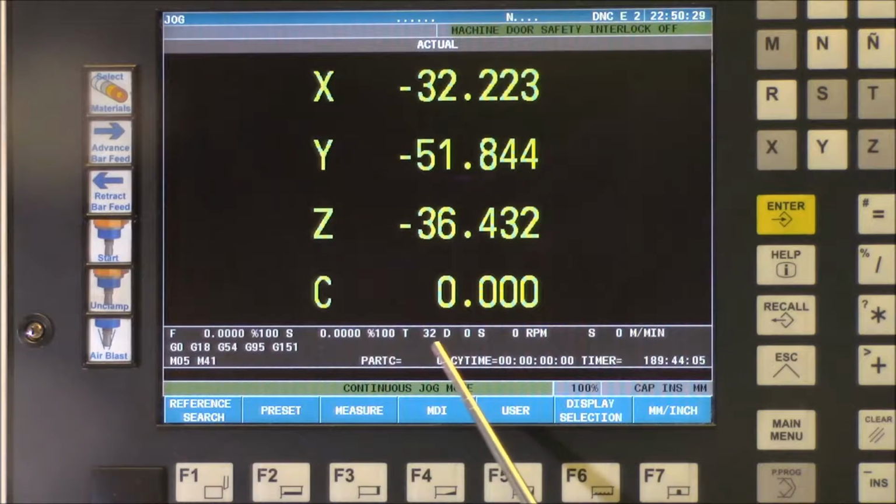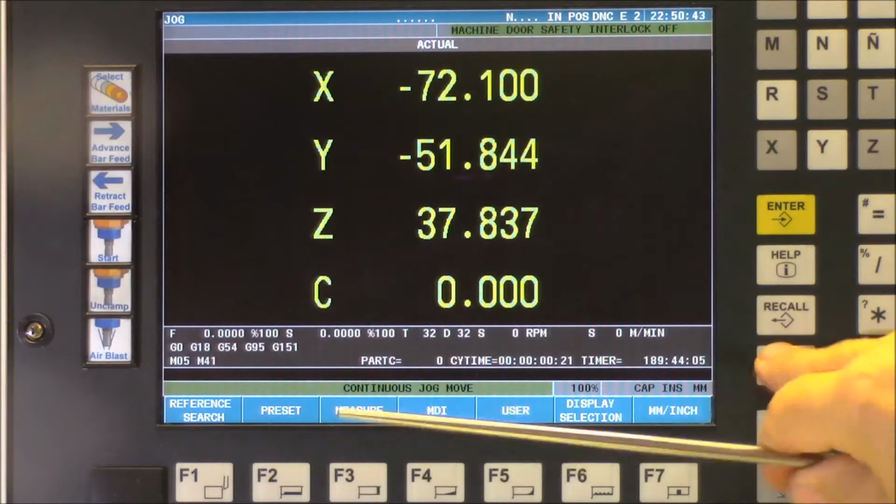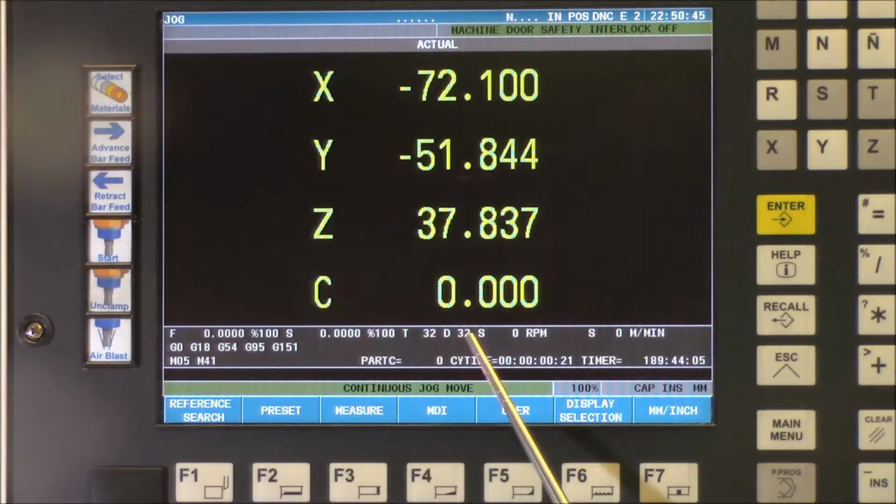This portion of the line shows the tool offset and the table offset. In most instances on the CNC, go to MDI 232, cycle start. These display the same number. In certain situations using form tools, it's possible to use a different tool number, but in general, the T number and the D number are always the same.